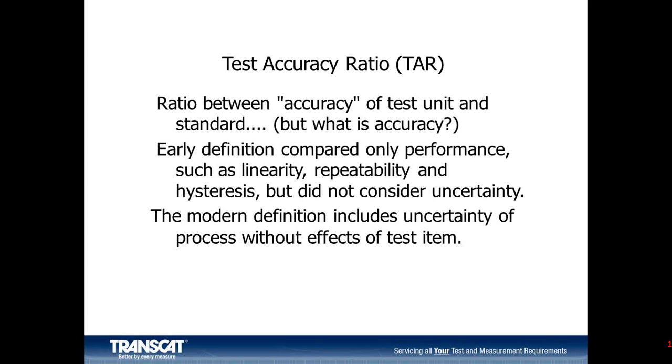But when it comes time to assess the uncertainty in the calibration of that test instrument, the complete uncertainty had to be included. What that means is that the 0.003% rating of the test instrument could not be used to represent its uncertainty.